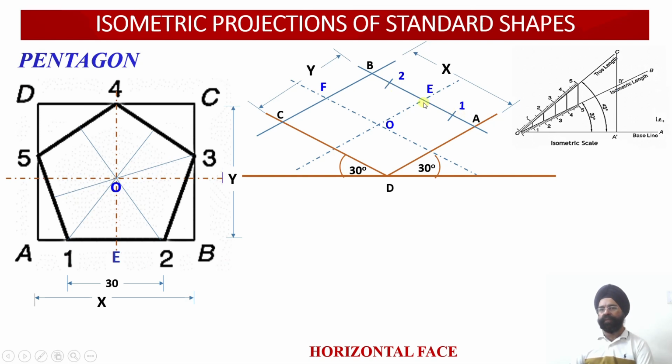So the 2 points of the pentagon have been evaluated, and besides this, you see, I have even evaluated the axis point of this, because we are going to need this while we go for the construction of the solids. From every corner, I have drawn the perpendicular bisector of the opposite edge. Wherever the 5 bisectors meet, the axis point will be located. But once again, this axis cannot be transferred here directly.